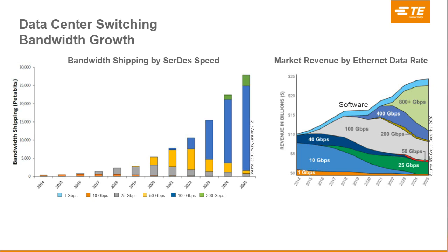Sure. Yeah. Of course, it would be nice if you could just turn up the dial on speed and everything would be okay. But the reality is, increasing speed brings with it many other challenges. For instance, when you increase speed, you're naturally going to increase the power dissipated, which puts significant challenges on the thermal design of the system. Other items such as EMI are just another example of some of the pressures that come with increasing speeds.